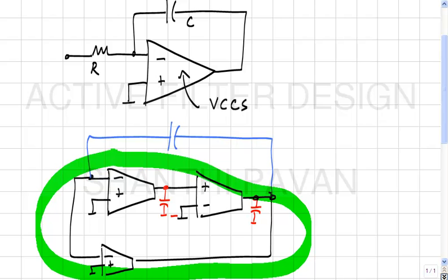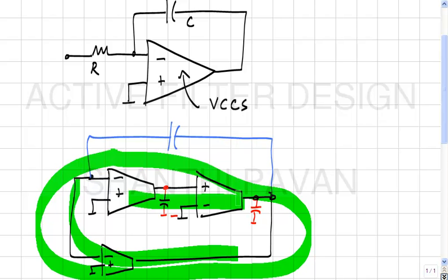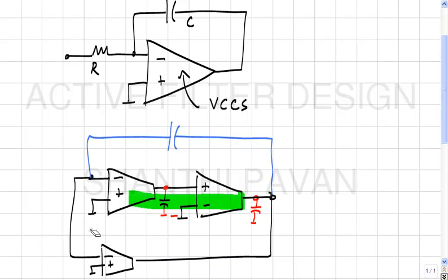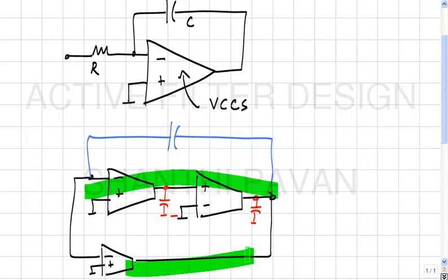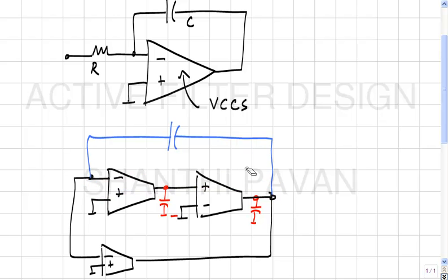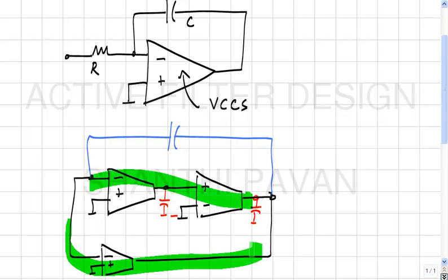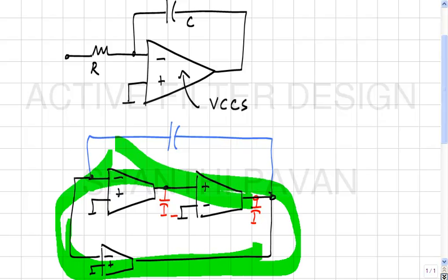which at high frequency basically looks like a single transconductor because this guy is too slow to react, right. Whereas at low frequency you have very high transconductance because this current will be dominating over this current. So, this is a way in which you have the advantages of both the high gain stage as well as the high speed stage, because this high speed is simply because there are no internal poles. Okay. So, this is nothing but what is called a feed forward compensated